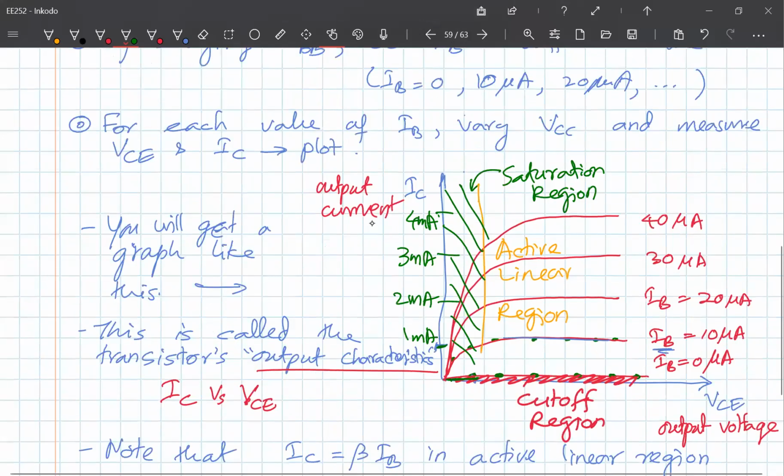But in addition, what happens if you have too much energy dissipation, like when the current as well as the voltage is high, for example in regions right above here, where VCE times IC, that is the power, right? Power is equal to VCE times IC.